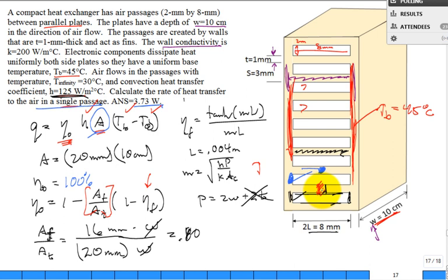It's all the 2 W's. And then the cross-sectional area for conduction is our thickness t times W. And so for our rectangular fin, you get h divided by k, but the ratio of P divided by A sub c is 2 divided by t. It's even simpler. Just 2 divided by t. What was t? 1 millimeter.